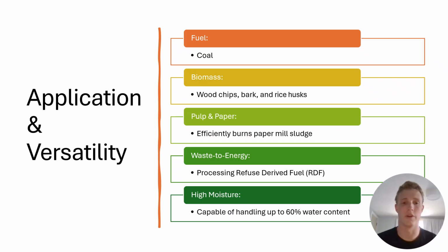It's a renewable energy product created by processing industrial waste, specifically non-recyclable paper, fibers, wood waste, and plastics into a high calorific solid fuel. And that's the nice thing about these power plants: they can use fuels with up to 60% water content, because they use a high temperature bed of sand that dries and ignites the fuel before significant heat loss occurs. The bed consists of sand, ash, and fuel maintained between 700 and 1,000 degrees Celsius. And like I said, when wet fuel enters, this high temperature immediately dries the fuel and initiates combustion.